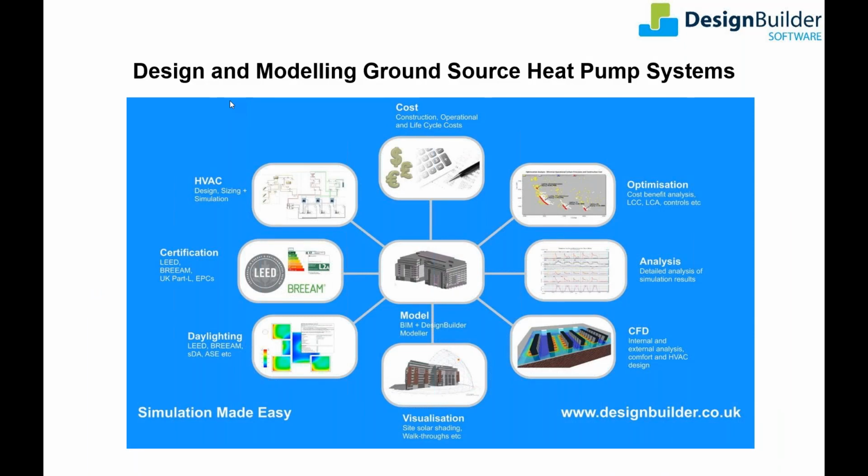Our primary aim today is to give you a succinct overview of some key considerations when modelling ground source heat pump and VRF systems and how they can be modelled effectively to improve the design process. Although DesignBuilder gives you the ability to undertake all these common forms of building performance modelling and simulation, today we'll be focusing only really on the EnergyPlus detailed HVAC tools specific to these systems.